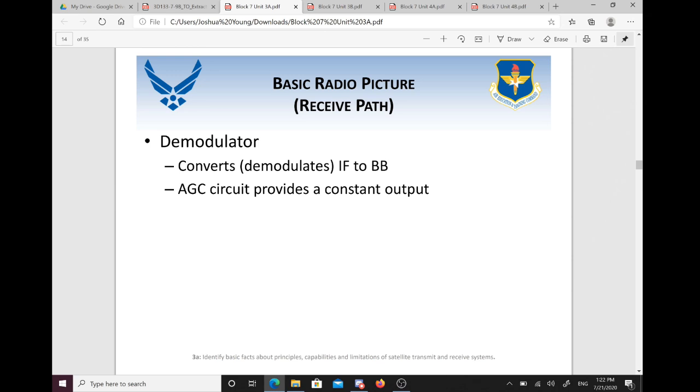Right. So it's the gain applied to your signal across a circuit or cable run, and it's all based on how strong or weak your signal is being interpreted by that circuitry. If your signal is weak, automatic gain control will boost it. But if your signal is coming in too strong, it takes power out of it so that it doesn't fry your circuitry where it has to go through. Does that make sense? So it's just an automatically occurring form of gain control, AGC. Does that make sense to everybody? Yes, sir. Cool.